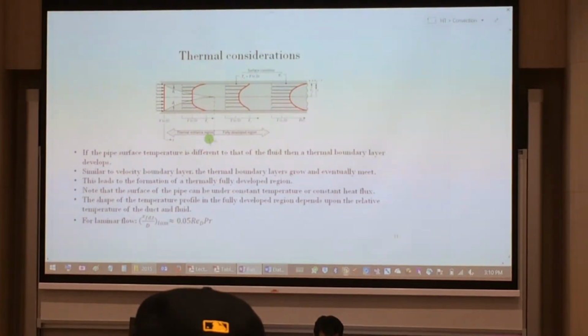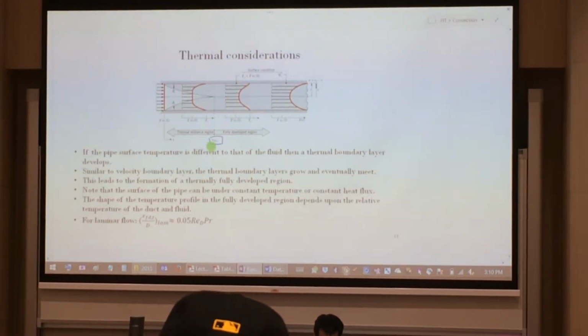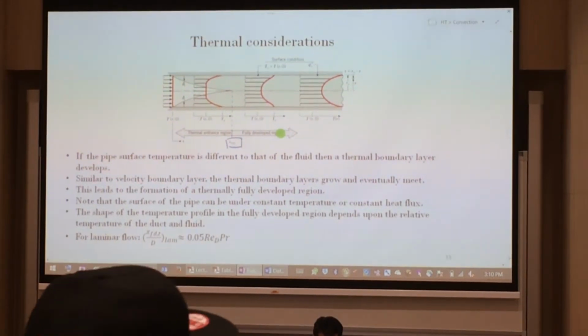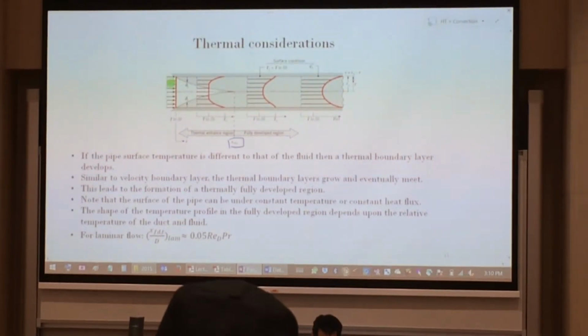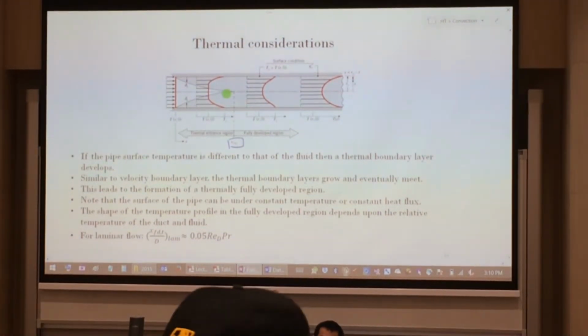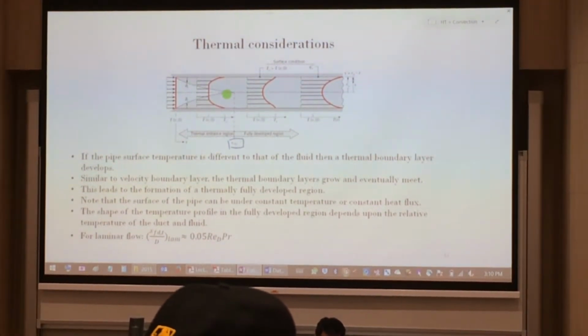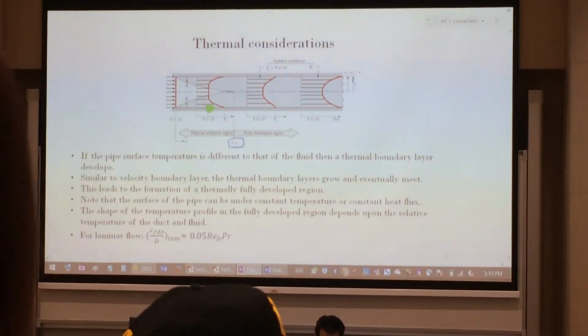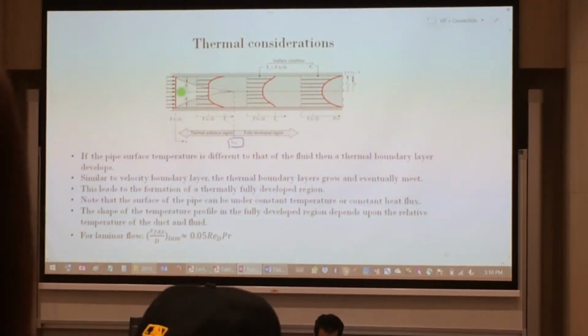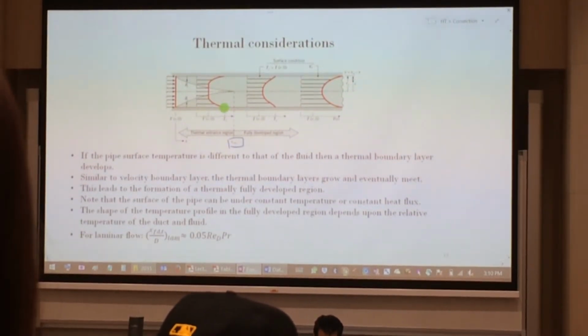Please note that for your thermal profile, there's still going to be your x_fd,h. The temperature that's coming in, or the flow that's coming in, will carry some temperature. You will see that if we assume that this wall temperature is higher than the core temperature of the fluid that's flowing in, that wall temperature, being that the velocity is 0, will get heated up.